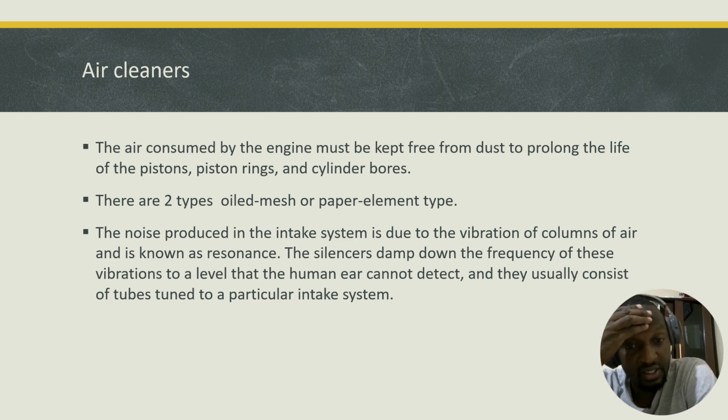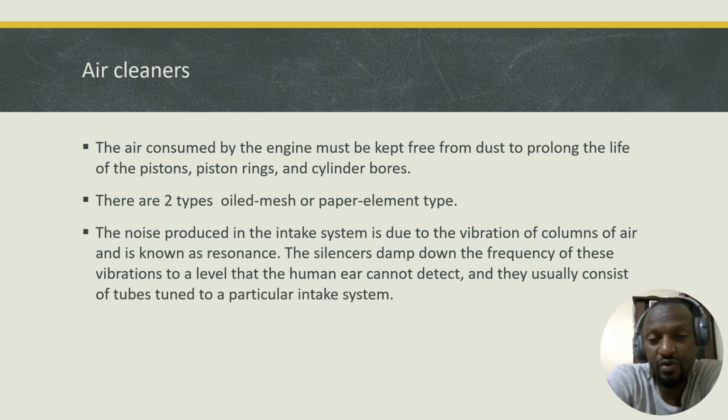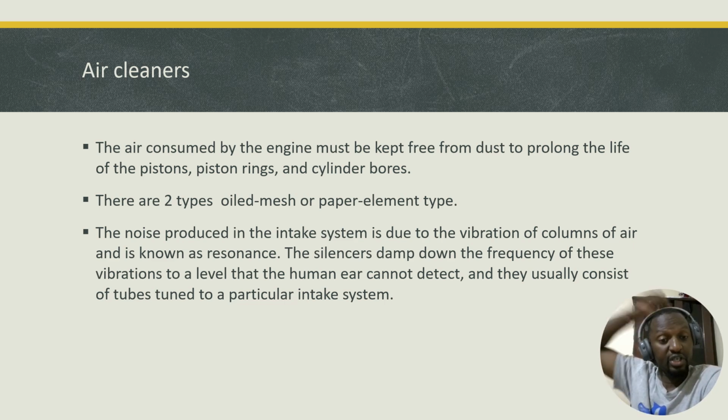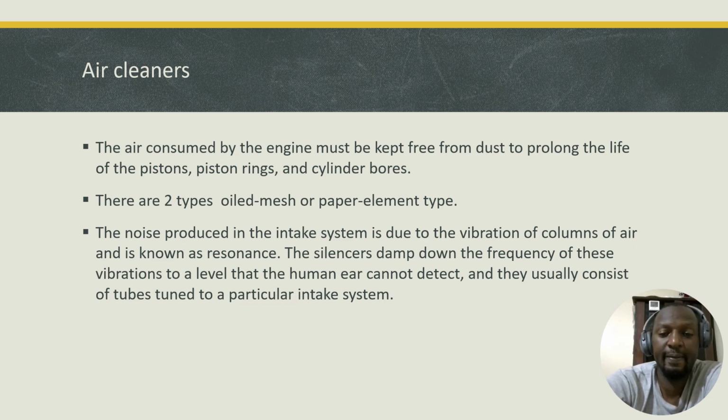Now the noise produced in the intake system is sometimes due to the vibration of columns of air and is known as resonance. Now the silencers are responsible to damp down the frequency of these vibrations to a level that the human ear cannot detect, and they usually consist of tubes tuned to a particular intake system. So nowadays you'll see air cleaners with boxes below them or pipes below it with funny shaped containers. These are containers that are used to kill out the pulses that are created by air, or the columns of air as they are drawn into the engine, called resonance. And sometimes it can be very noisy if we are to draw air directly.